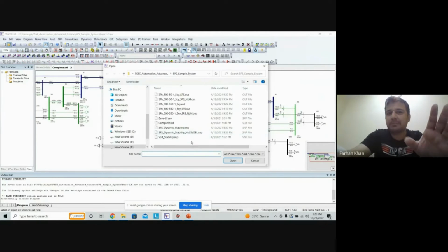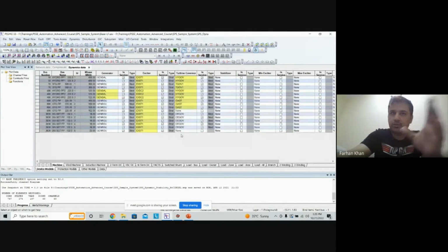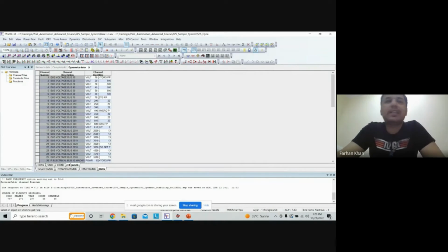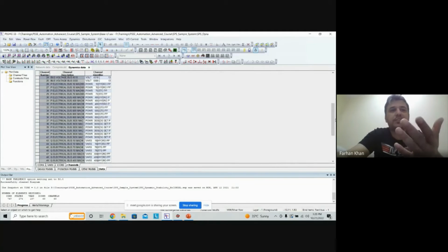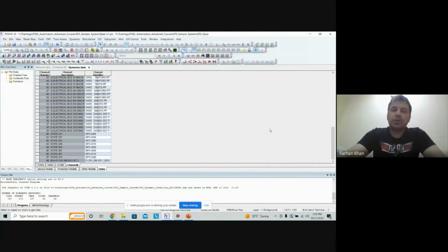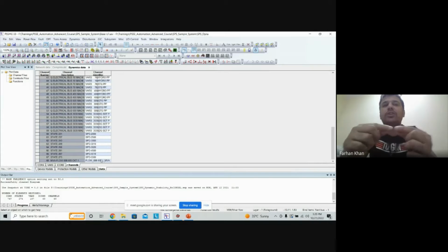And if I open the snapshot file for this, these are all the channels I have. You can see all the channels, again, as I told you, in sequence. All the voltages first, then P electrical, then Q electrical, and so on. Here, particularly, what I want to monitor is the MVA flow, right? So that is why I have this channel, and this is the quantity I'm going to measure.